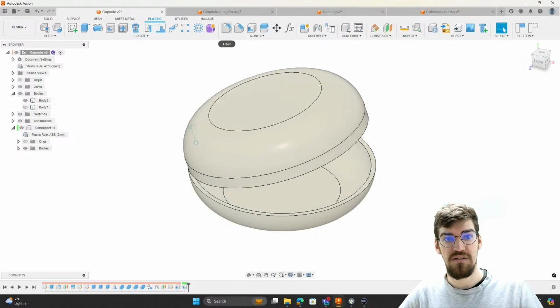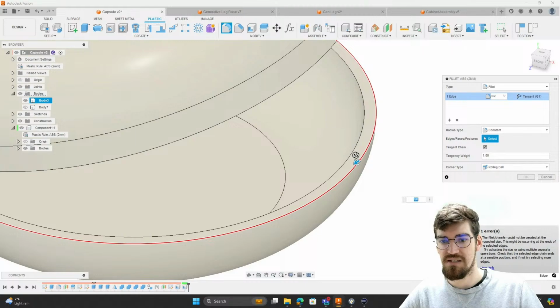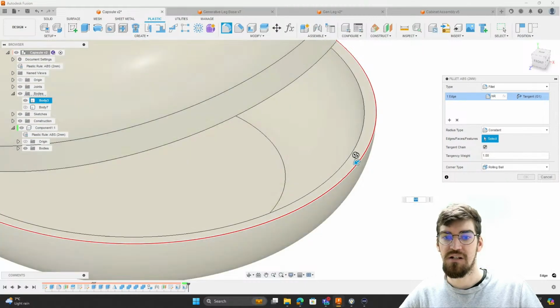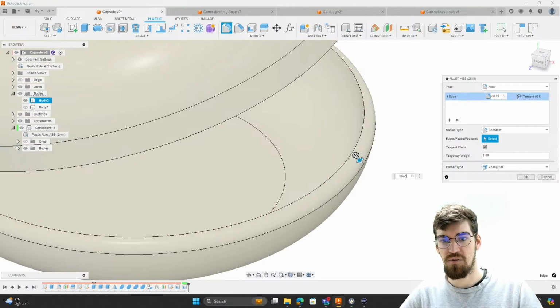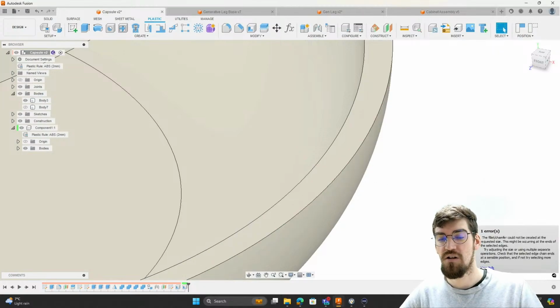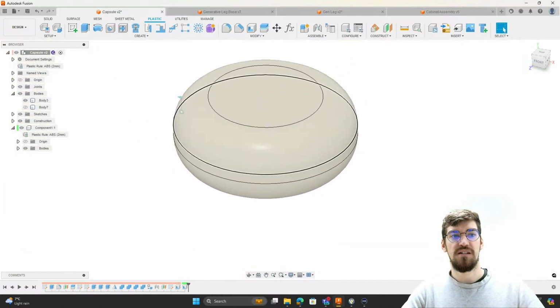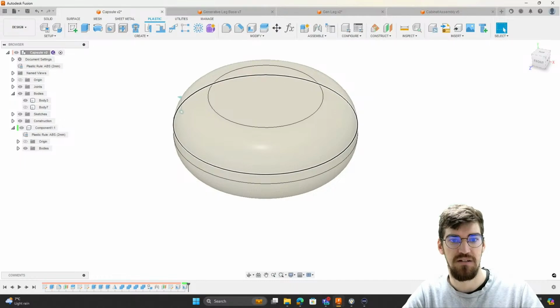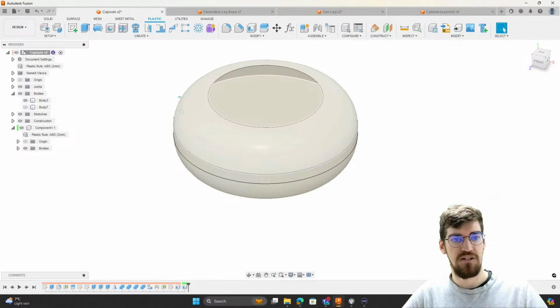That will also include fillets. So if I grab a fillet and add a fillet to the external surface over there, I've got a nominal radius that it wants to apply immediately to that corner. In this case, it might be a little bit small, so I can use the equation to place in a nominal radius that's half of that value, or any other fractional value of that nominal radius. So that really assists us in the creation of certain features from inside of the design environment.